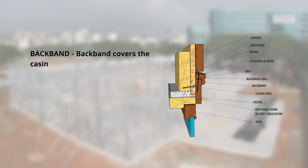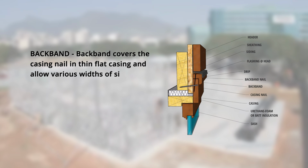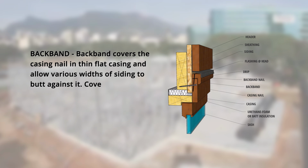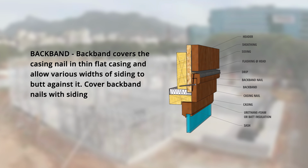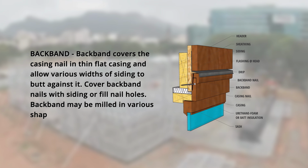Windows. Backband. Backband covers the casing nail in thin flat casing and allows various widths of siding to butt against it. Cover backband nails with siding or fill nail holes. Backband may be milled in various shapes. Take a look at this detailed illustration.